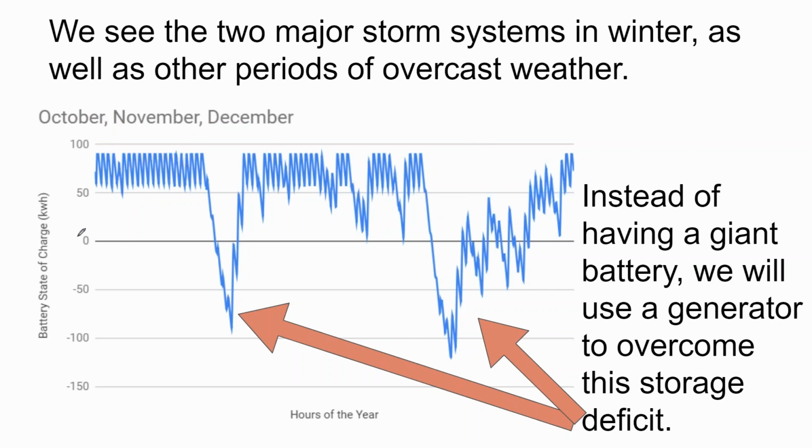And so instead of this being my zero line, let's just make it easy on us, if I added 25 kilowatt hours to the battery bank, now this would be my generator zero line. So instead of turning on the generator here, I would turn the generator on here and run it for less time, but I've also spent more money on my battery bank. So then the question is, the generator, is it used to just charge the batteries or to power the house?